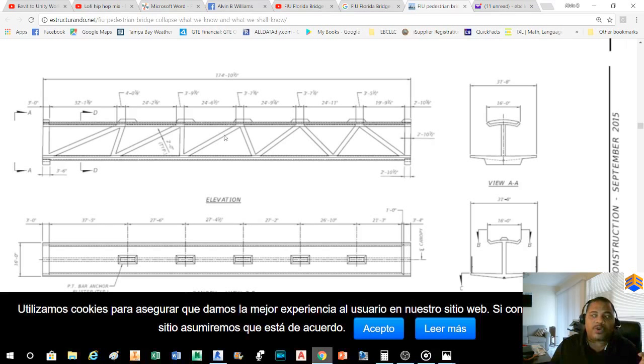But if this beam were to experience tension, being pulled apart, then once that particular web fails, you try to build in redundancies to always have a plan B. But this particular web might have been loaded in such a way that once it fails, that puts extra strain on everything else. And then once the next component fails, and the next component, and so on, before you know it, the whole thing comes down.